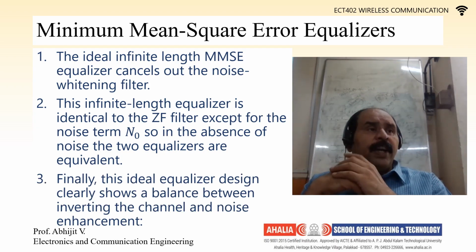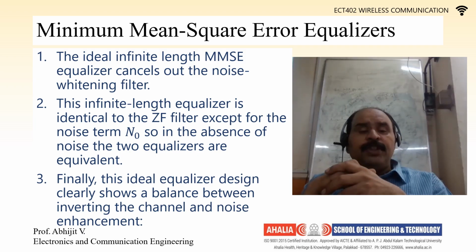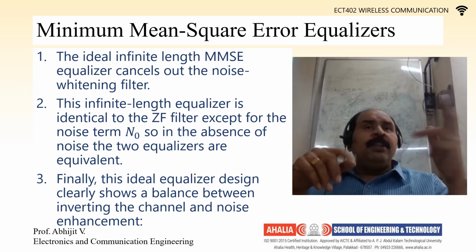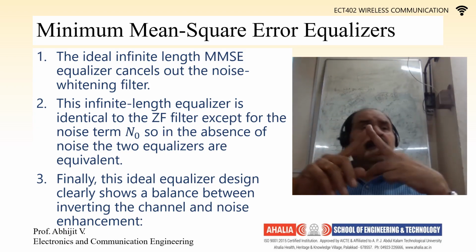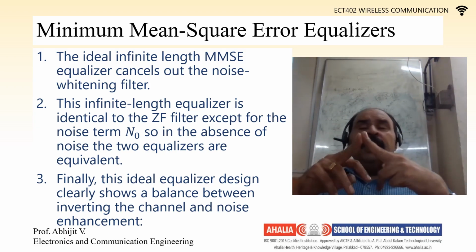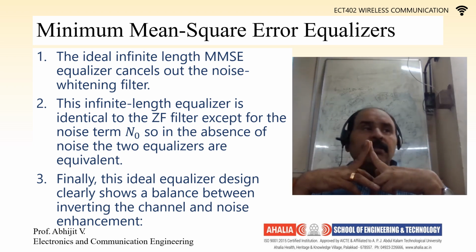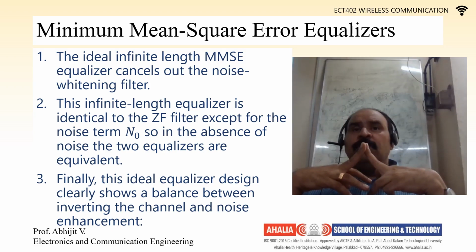The third and final point is that an ideal equalizer shows a balance between inverting the channel and the noise enhancement. We have seen that the zero forcing filter eliminates ISI completely but enhances the noise, right? Yes or no?